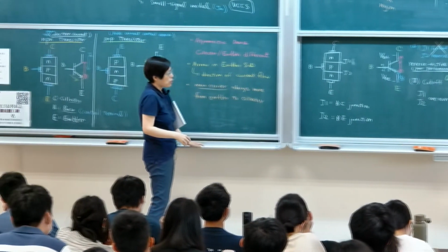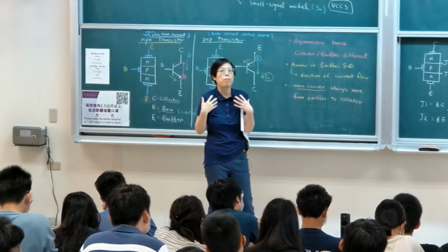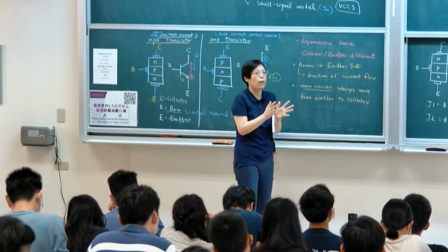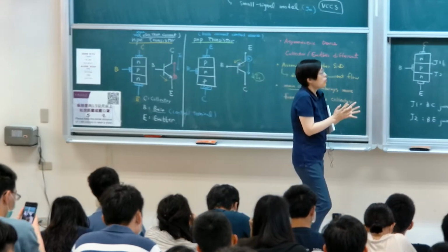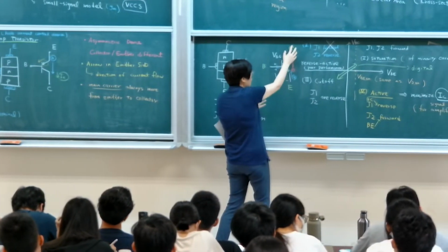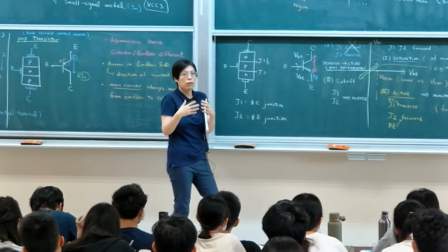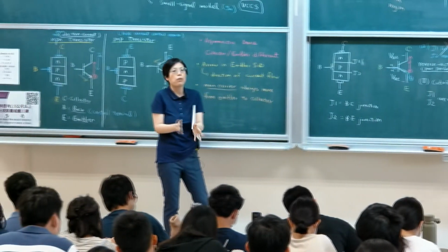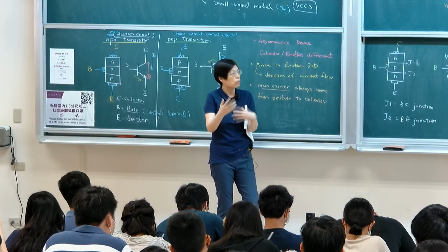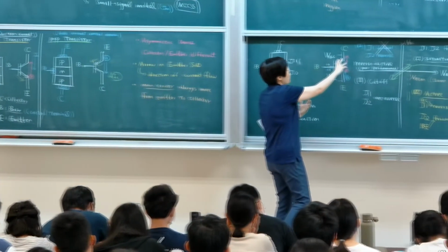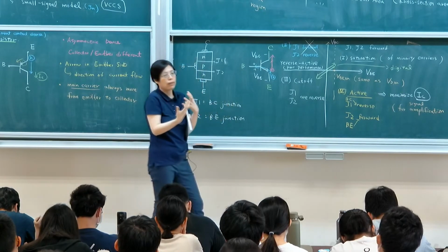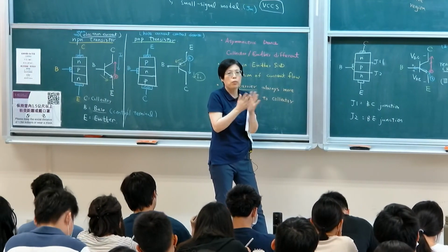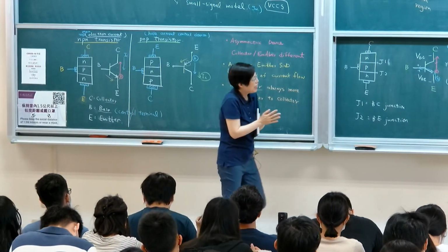That's what a bipolar junction transistor, when it operates in forward bias in active mode, is actually doing: splitting the two types of carriers, the two types of currents. It selectively only sucks electrons. Rather, it will push away holes, which then go to the base. Separating these two allows you to have better control of your main current, which is this electron current. How we maintain that will be the topic of our next lecture. That will be very interesting, so make sure you come. I think it's very interesting.